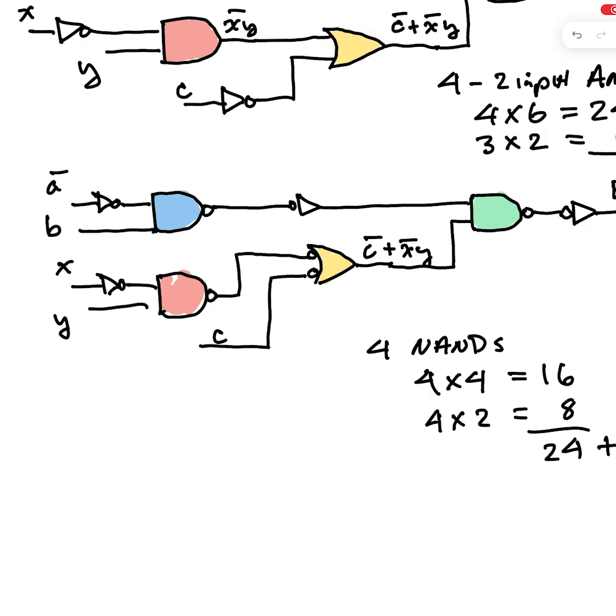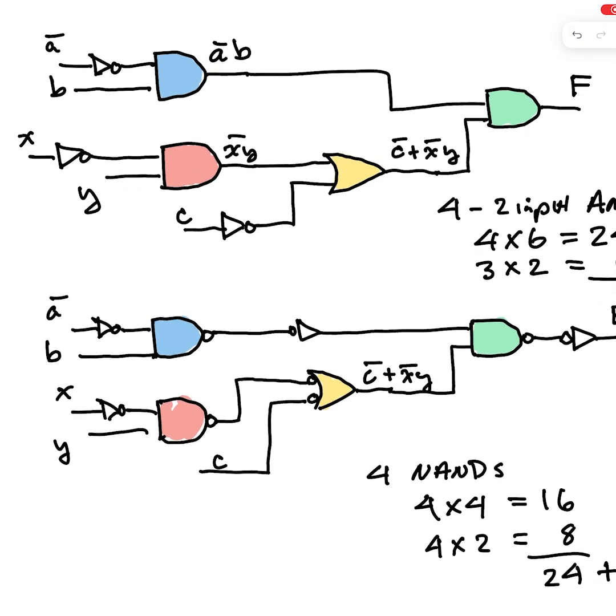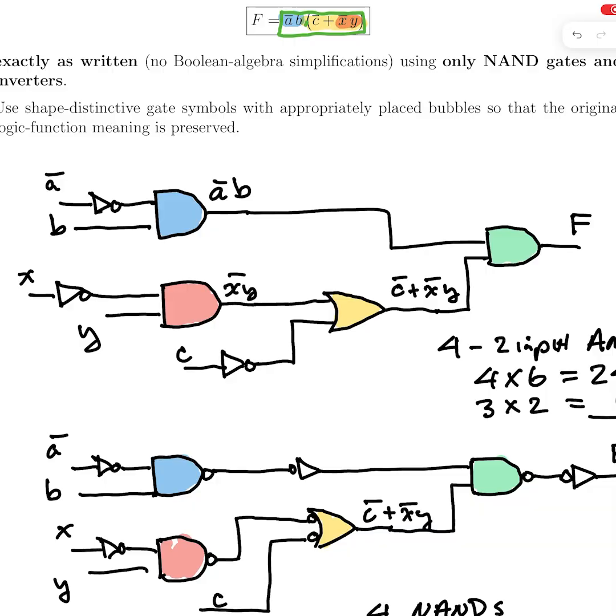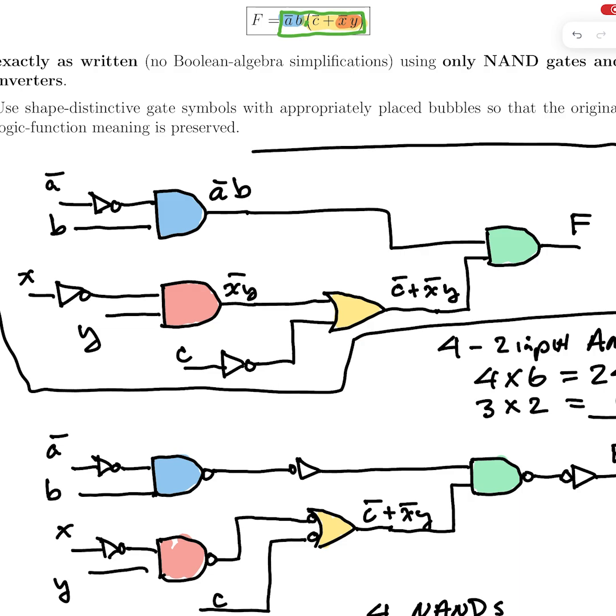Okay, so I like to think of this in levels of abstraction. When you have a Boolean function like we have in this example, this is my natural instinct of how you would implement this. But when I look at this circuit, in my mind, I know that it can be converted to all NANDs, and you could implement that more efficiently.